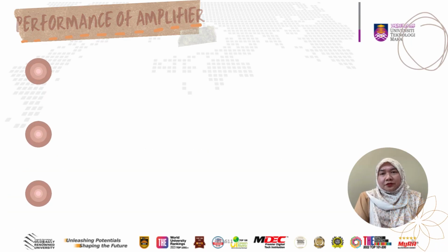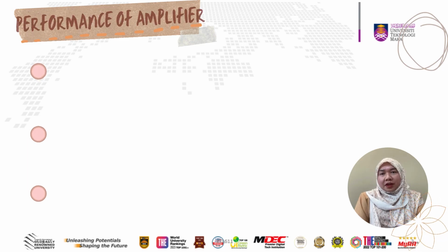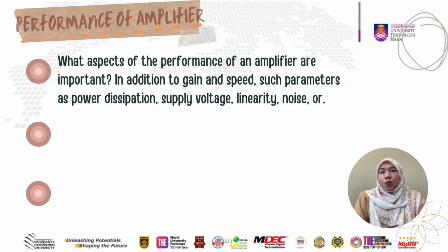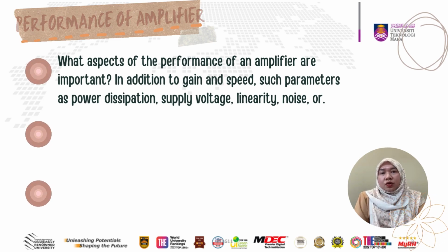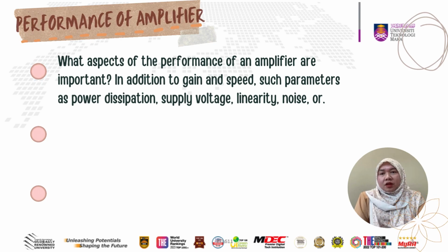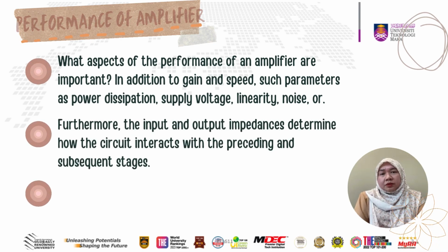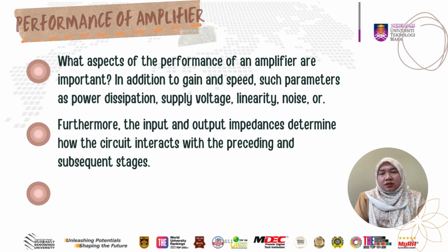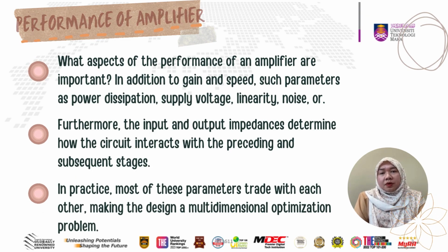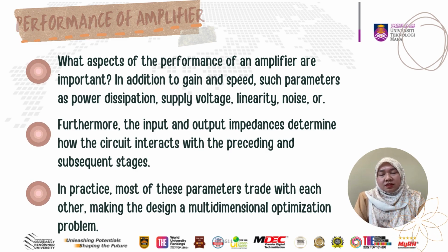It is also important for you to know performance of amplifier. The first one, what aspects of the performance of an amplifier are important? In addition to gain and speed, such parameters as power dissipation, supply voltage, linearity, noise, and etc. Furthermore, the input and output impedance determine how the circuit interacts with the preceding and subsequent stages. In practice, most of these parameters trade with each other, making the design a multidimensional optimization problem.